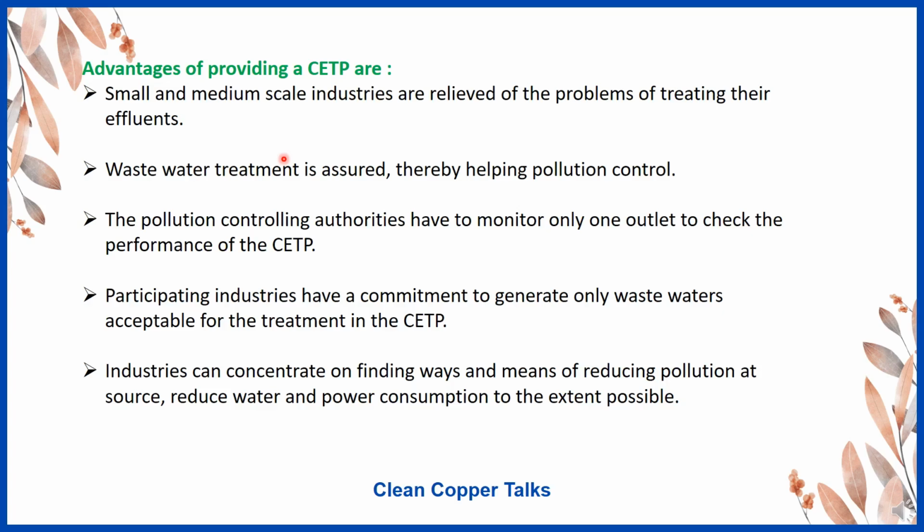Participating industries have a commitment to generate only wastewaters acceptable for treatment in the CETP. So the participating industries should do their preliminary treatment before sending it to common effluent treatment plants. Industries can concentrate on finding ways and means of reducing pollution at the source, reducing water and power consumption to the extent that is possible.